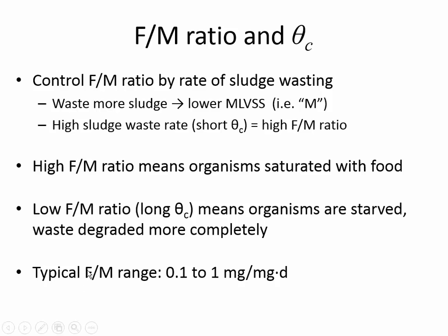If we look at it in terms of food to microorganisms, 1 milligram of food per milligram of suspended solids per day would be a lot. Think about that. How much do you weigh? Maybe 70, 80 kilos, right? What if your food to mass ratio was 1? What that means is, what if you were eating 70 or 80 kilograms of food every day? That would be a lot, right? We can't do it. The bacteria have a bigger appetite than we do.